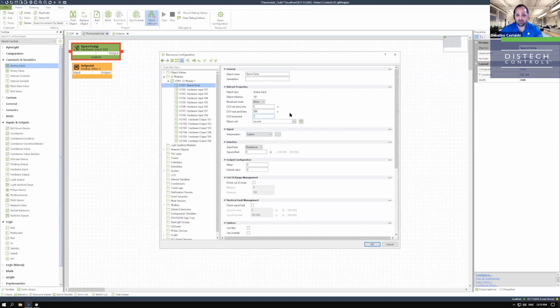And this is a good time to talk about Niagara. If you have a Niagara-based environment where you're constantly asking points or controllers what their values are, take into consideration that we're not going to tell you anything faster than 5 seconds anyway, and that's by design for easy use of network traffic.